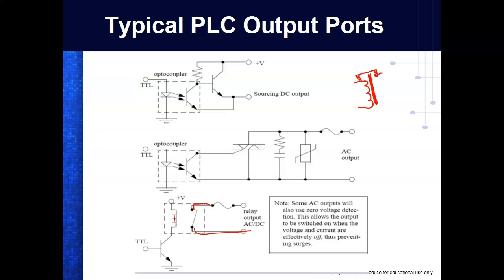So the starter on your car has a starter relay. It's built into the starter. It's really, really neat. There's no way in the world your starter's running through your ignition switch. And of course now we've got push buttons where you don't have a key, you have a fob that you carry around in your pocket. When you get close enough to your car, you press a button and it starts. Well, there's no way in the world that button's going to control your starter. It's going to be a relay.